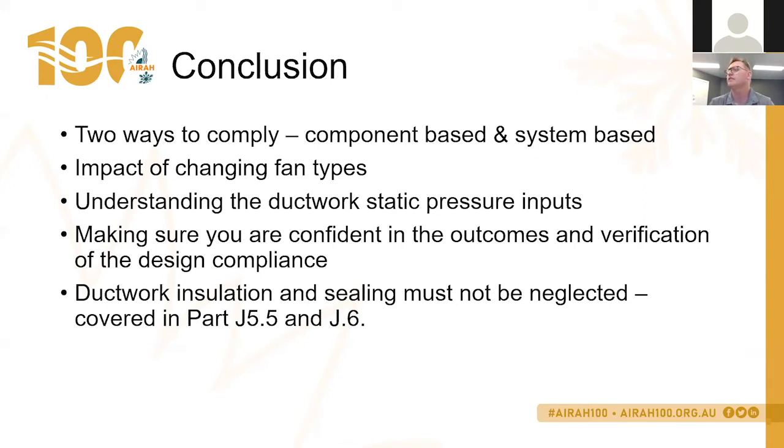We always have to consider absorbed power at the duty point to meet compliance, not nominal capacity of fans, correct? Can I just type correct? How's that? Does that answer that question? Yes, we do consider the absorbed power at the full load operating point. And well, it's the absorbed power plus motor losses.